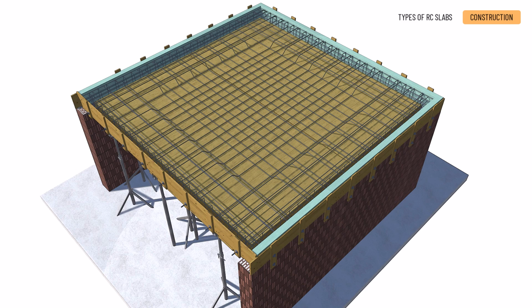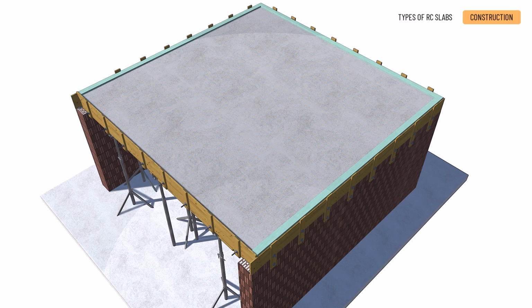Concreting. First, before starting, the structural engineer checks the reinforcement and the formwork alignment, and also its penetrations, e.g. water pipe. Second, mark the top level of the concrete on the inside of the ring beam formwork. Third, pour concrete with a concrete pump from a mixer truck, preferably uninterrupted, in one single pour. Fourth, work the concrete by hand to spread, compact and smooth it.